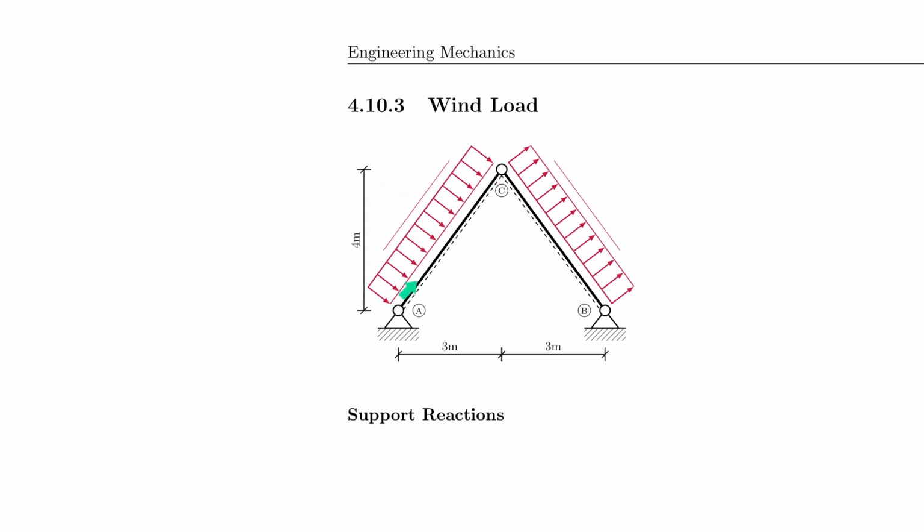Of course, it depends highly on the pitch of the roof, but you have wind pushing in on one side and pulling on the other side. And so this is not a symmetric system anymore. It's a little bit more challenging, but also a little bit easier, because now all your forces are actually 100% perpendicular to the axis of the beam. So there's no parallel component in this case. So that should make life a little bit easier.